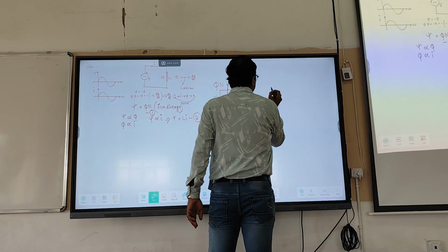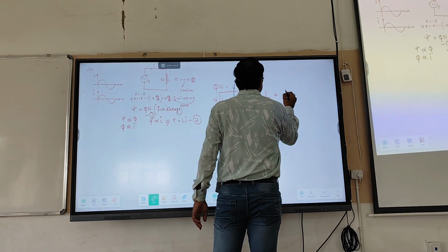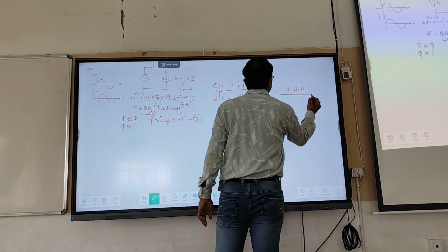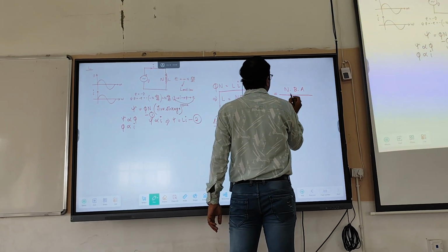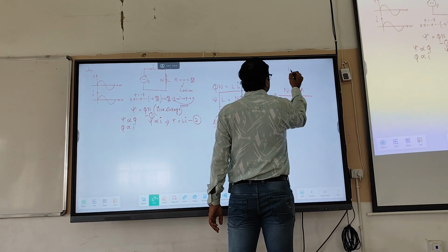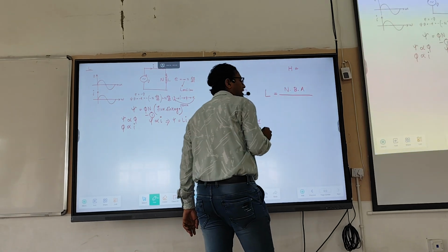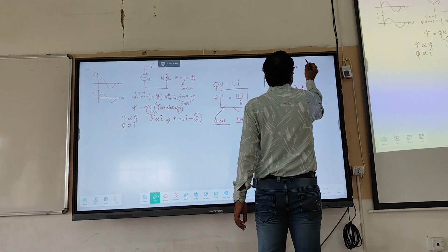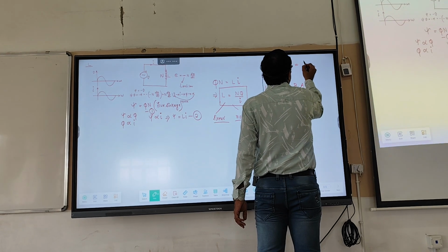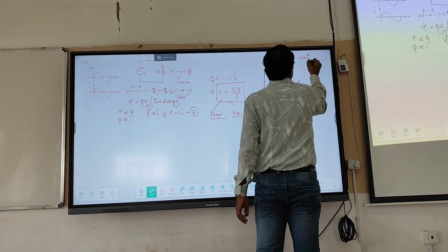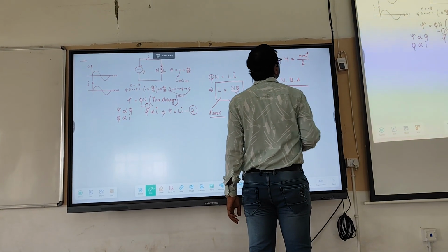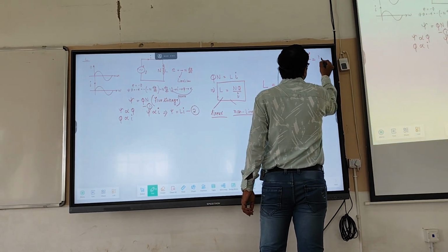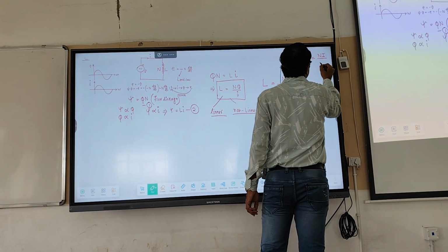So L, I can write as N into B into A divided by I. What is I? H is equal to magnetic field intensity, equal to mmf divided by length of the core. What is mmf? N i divided by l.